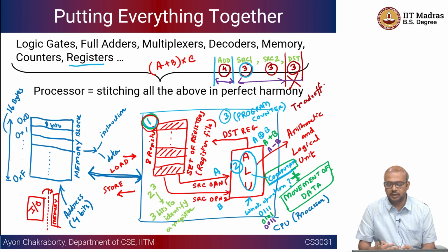Logical operations could be XOR, or let's say AND. You want to do a NOT or an AND or an XOR, and so on. So based on the control inputs to an ALU, which is basically a set of bits that identifies the operation that an instruction is trying to do, the ALU is going to select one of these circuits. So if it has four circuits, let's say one for addition, one for subtraction, one for AND, and one for complement, NOT.